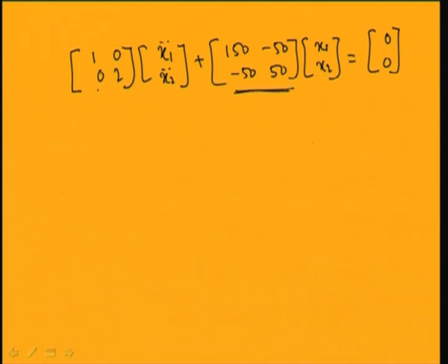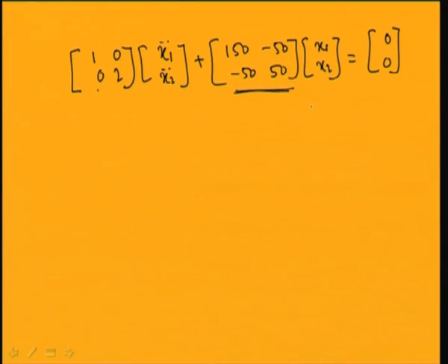This is static coupling of the system. As it is statically coupled, x1 and x2 are not the principal coordinates. So, we have to find the coordinate y so that both the mass matrix and stiffness matrix will be uncoupled. To do that, we should find the normal modes, from which we can find the modal matrix, and using that modal matrix we can find the principal coordinates.